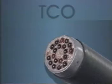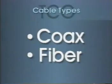We could put in bigger copper coming to your home. We use larger copper tubes in the inner part of the telephone network where we're carrying large volumes of traffic. This is called coaxial cable. It's very thick center copper wires surrounded by a white plastic with a metal tubing around the outside. Quite similar to what you might see if you looked at the connection to a cable television to your home. But that's a lot more bandwidth or a lot more transmission capability than you need right now. So those two wires really do the job. But we could put in coax if you needed more, which is the big thick copper wire. Or the new technology is we could put in this fiber optic cable.